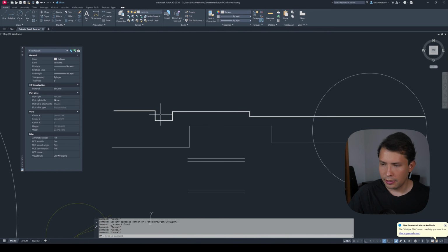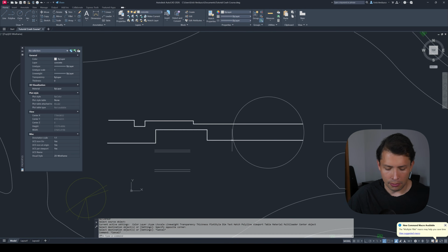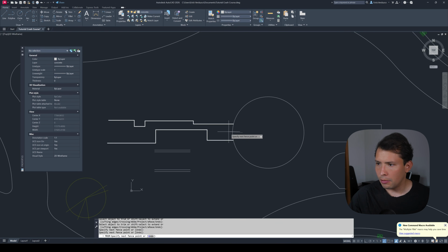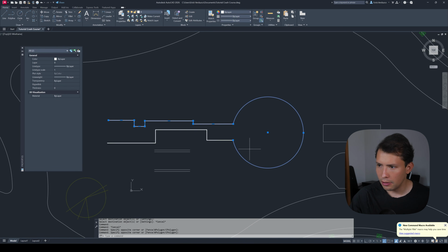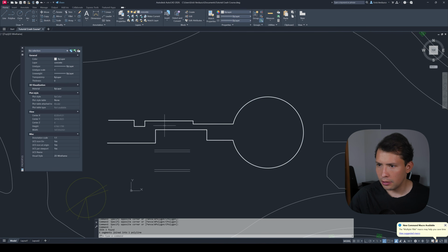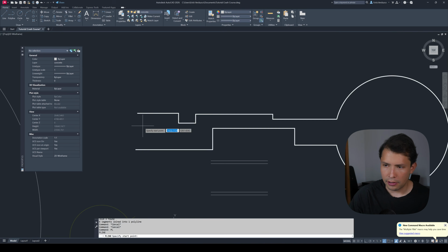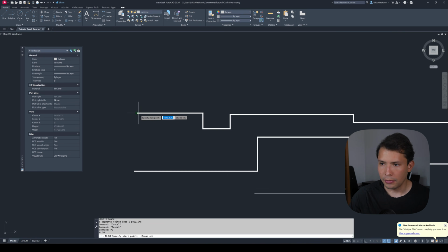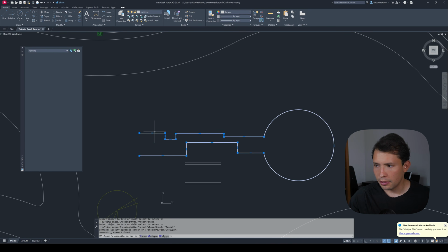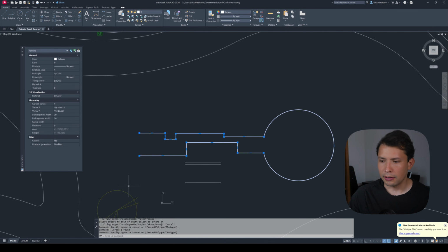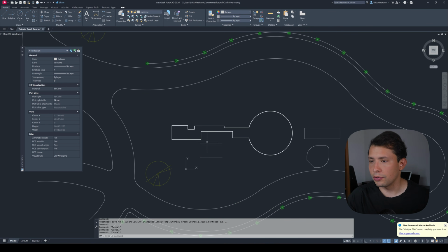First, I'm going to bring this line to a width line as well, and I am going to trim right here. I'm going to cut right here, select all, join it all together, and then I'm going to show you a nice trick to close these two polylines. The first thing that you could do is go from this point up to this point, and then trim as well right here. But another way of doing it is to select this polyline, and on the properties panel, click on yes, and that will automatically close the polyline.